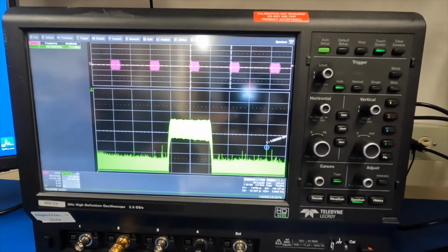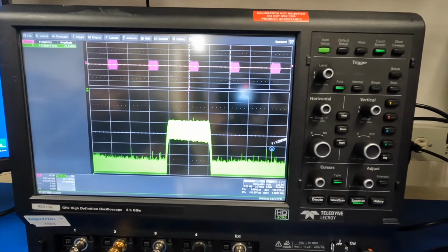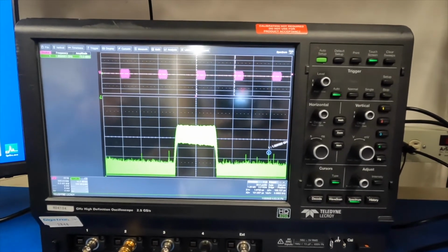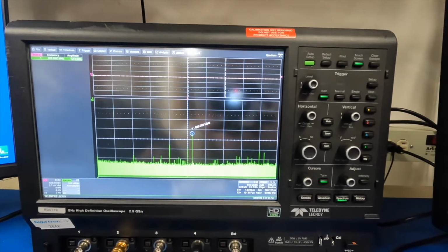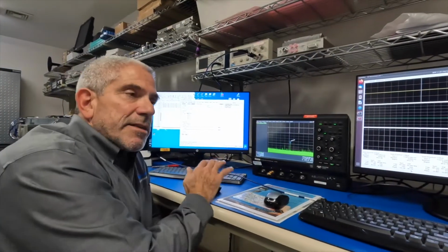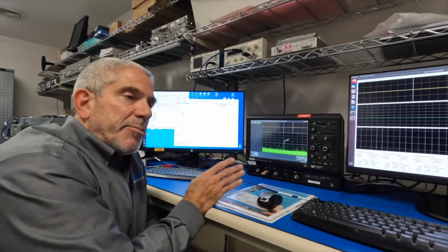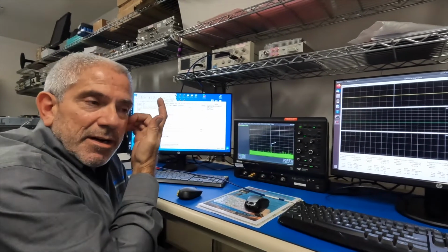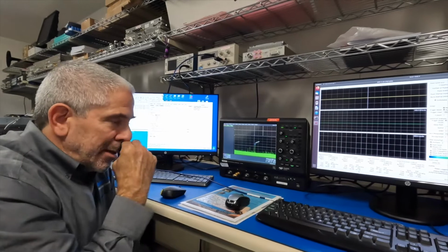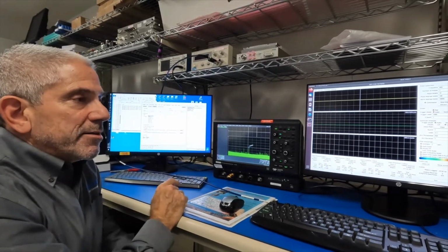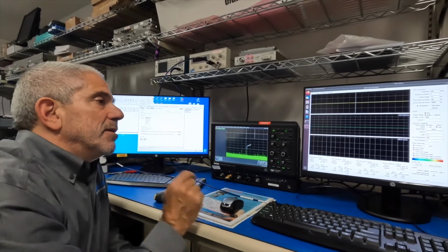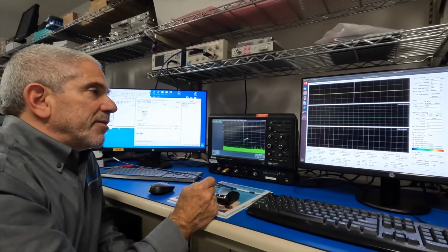And we're going to put those 3 different center frequencies through the received pulse parameter extraction. Okay, so we're just going to cycle through same pulse width, same PRI, 3 different center frequencies. We've already piped it over to the RF SoC card for the RPP-PDW extraction, and we'll show you the real-time display of the PDW extraction with all the event processors and the displays in both time and frequency domain.